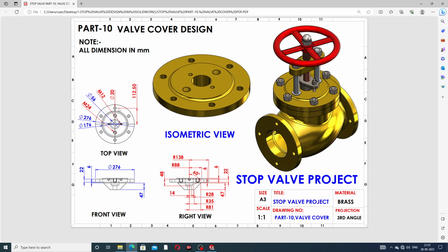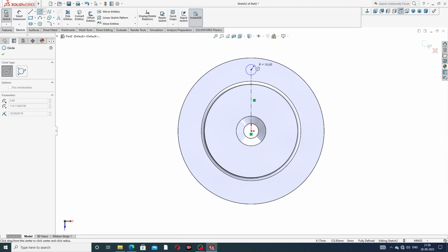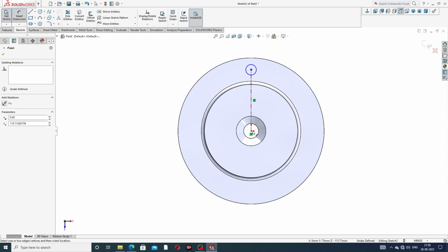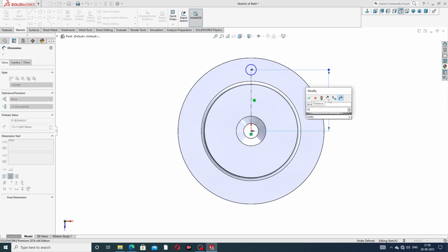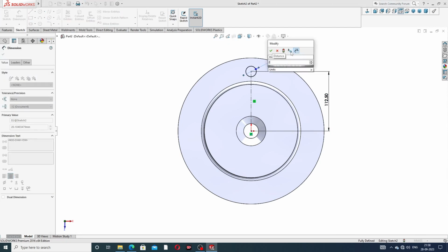Okay, and this is perfect and okay, this distance is mentioned here, but apply a thread and then the distance is 120. Okay, and use a circle, drawing here. And this is a vertical line, and the distance from this point to this is 112.5 millimeter, and this diameter is 20 millimeter.